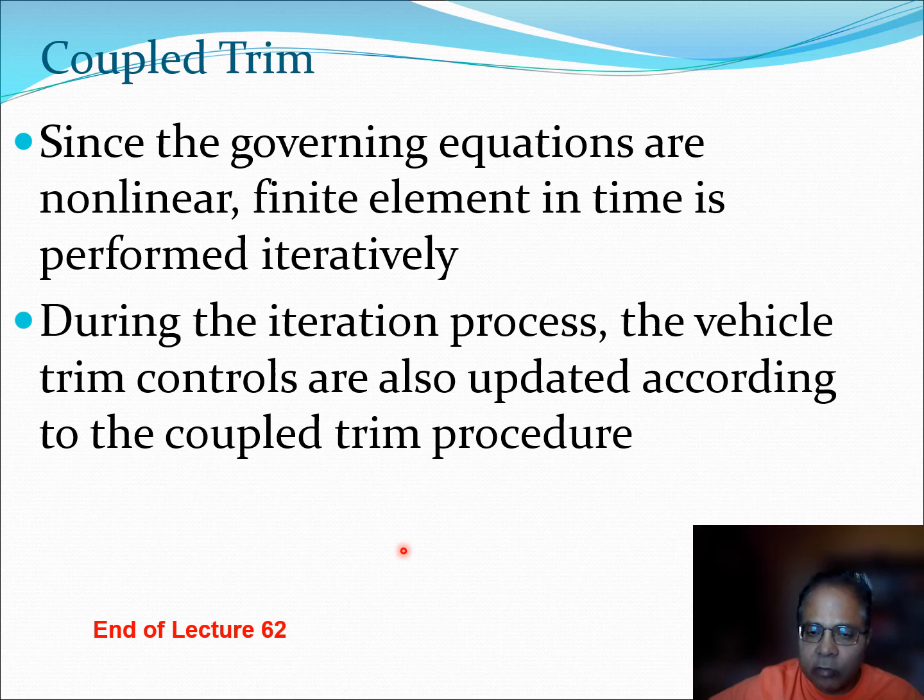One is known as the trim problem, which we will discuss later in this course. That's actually all the forces which act on the helicopter system must come up to zero. And the second is the response solution which is going on. So in some cases, these two things are combined, and that is known as the coupled trim solution. So you will hear that many comprehensive aeroelastic codes are using coupled trim, and essentially what they are doing is they are solving the trim equation simultaneously with the equations for the rotor blade. And so when you do that, you get very quick or reasonably quick solutions for the problem.